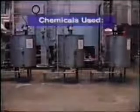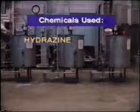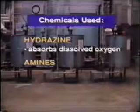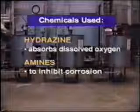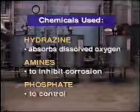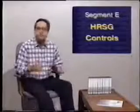Typically, the following chemicals are used. Hydrazine, to act as an oxygen scavenger, that is, to absorb any dissolved oxygen which is present in the feed water. Amines, which are injected into the condensate system so as to inhibit corrosion of the steel pipework. Phosphate, which is injected into the boiler drum to control pH. Now, we're mentioning here just a few of the most typical chemicals used and the conditions monitored.